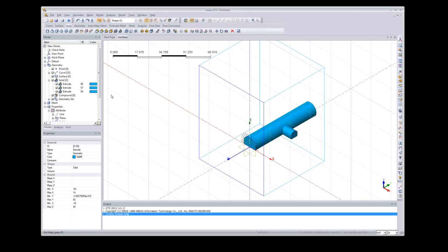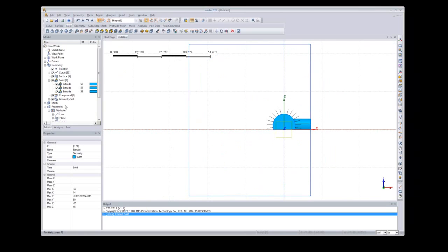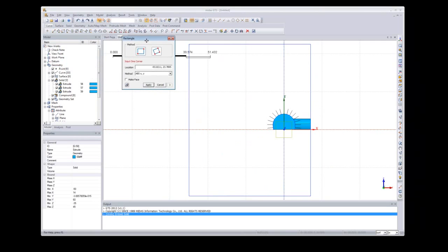Now we have to divide this tunnel into smaller pieces, because we have to excavate some part and then create the shotcrete, and this goes in this sequence. So for that reason, let me go here, and now go to the curve, creating a new rectangle.